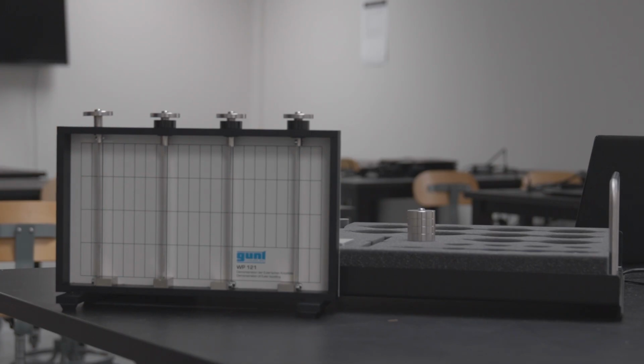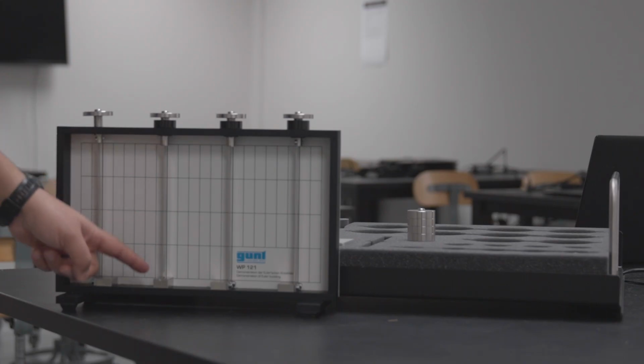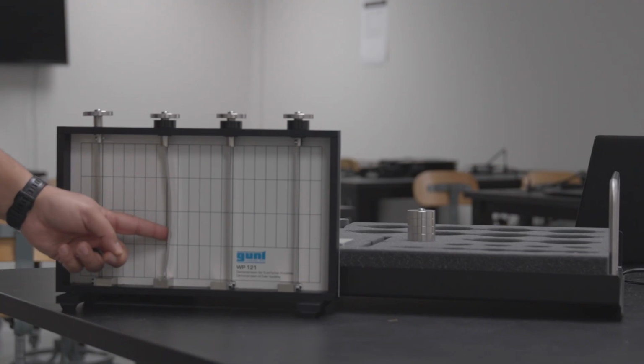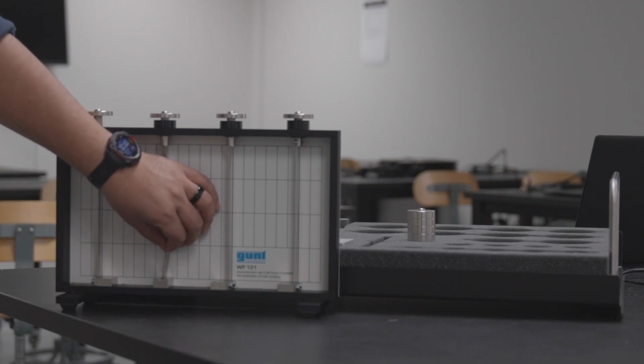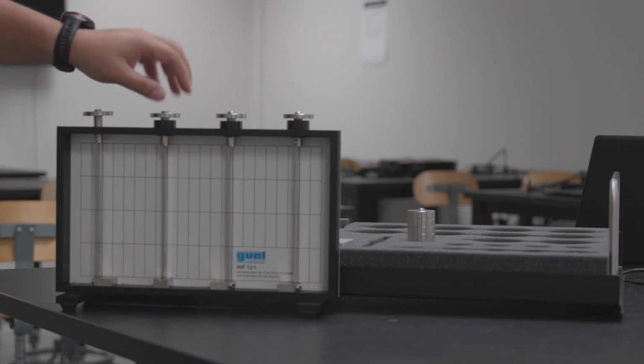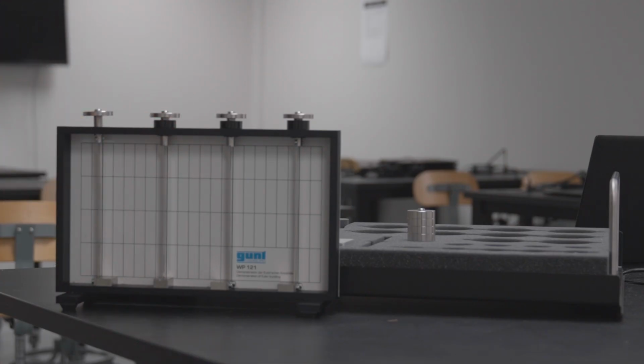And the second column has 2 pinned supports. What are pinned supports? Pinned supports are supports that do not see translation, movement in this direction, only rotation. If you see the movement here, we see a little bit of rotation here and also on the top, but there is no translation. There is no upward and downward movement.